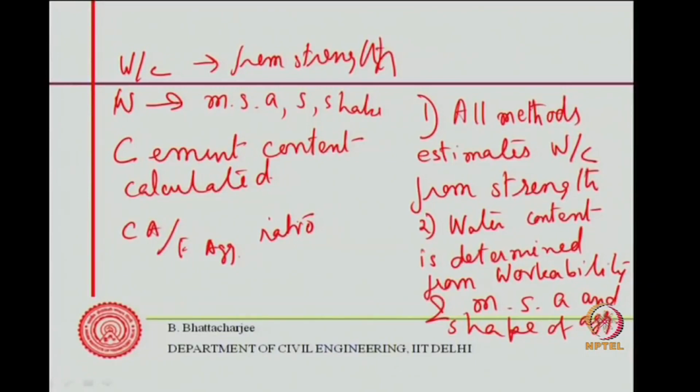Actually, strength is a function of water cement ratio. So, durability requirement, based on the chemical exposure, determines the water cement ratio, and strength also governs the water cement ratio. So, whichever is lower, you choose that water cement ratio.